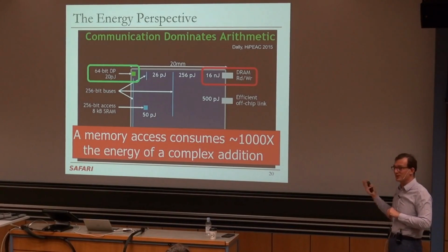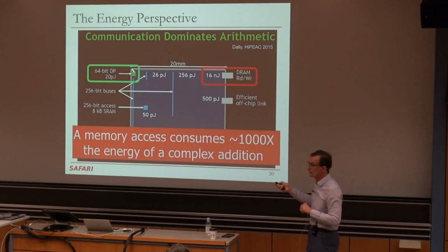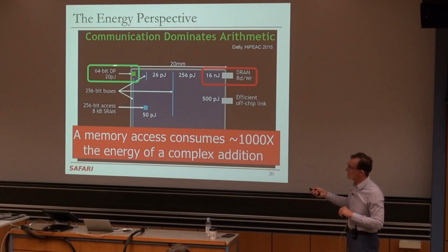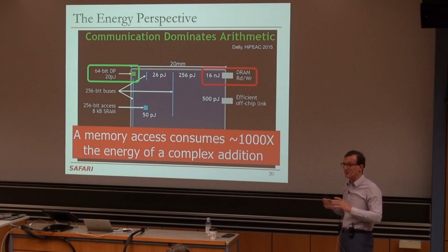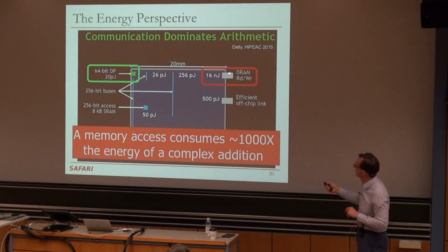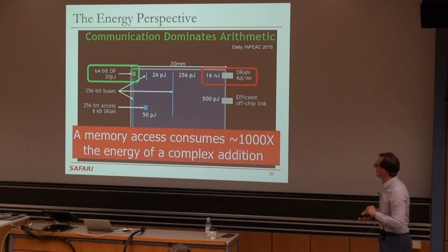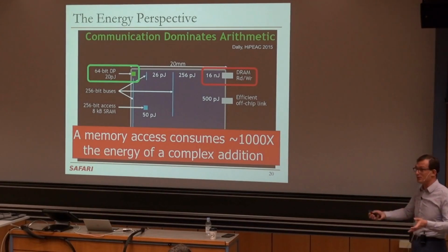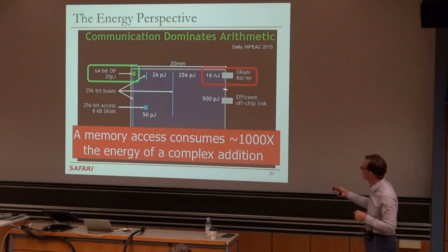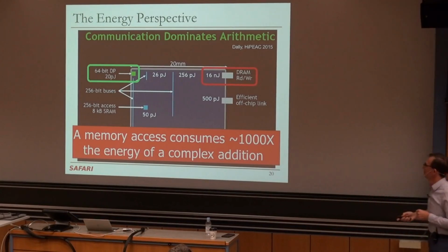You're doing basically 3 DRAM accesses to do very simple, well, relatively simple today, in terms of energy, computation. It may not make sense, right? You're basically exercising this huge disparity in terms of energy. Okay, so that's one of the motivators for doing something else. As opposed to processing here, maybe we should be processing close to the memory, such that we don't actually incur this huge energy cost, right?